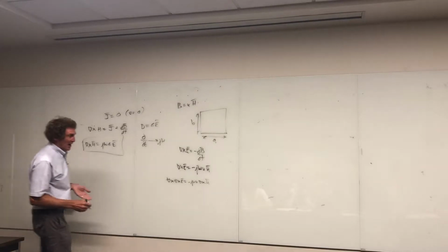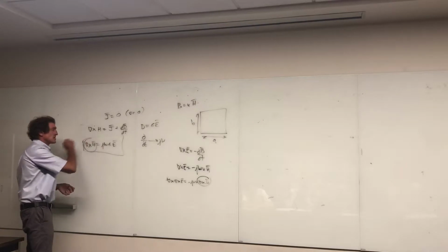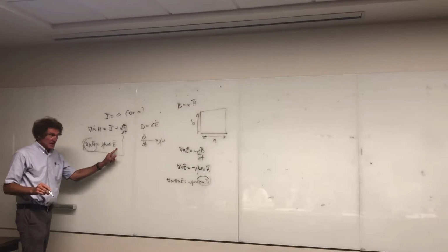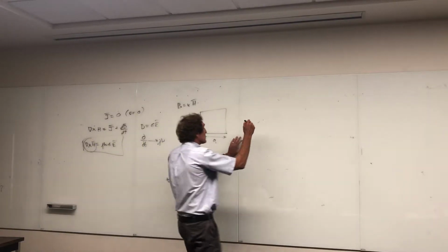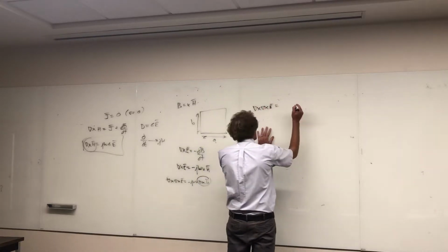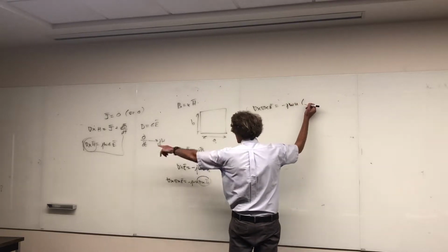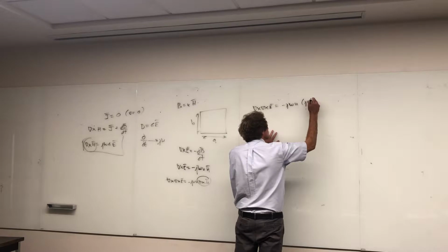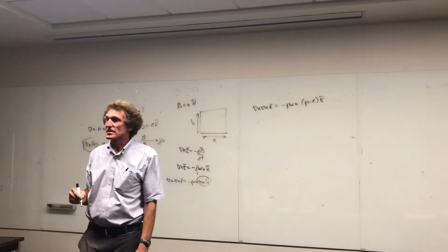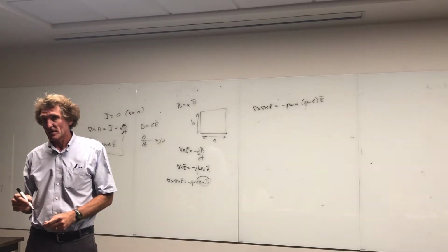Well, if you look at this right here, and you look at this right here, they're the same, right? So I'm going to take this, because it's just E, and put it there, and then I get curl of curl of E is equal to minus j omega mu times curl of H, and curl of H is j omega epsilon times E. I'm doing it for a reason. I'm making sure everybody sees this. You saw it last time several times. Now you're going to see it again.